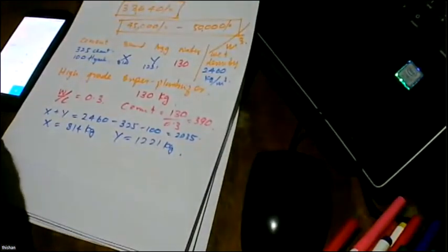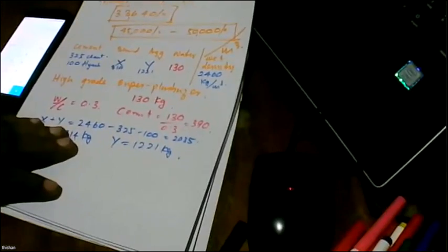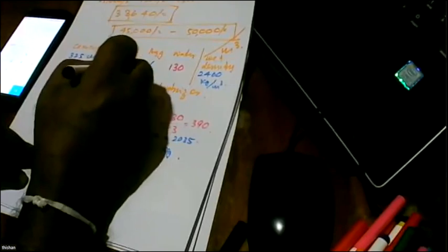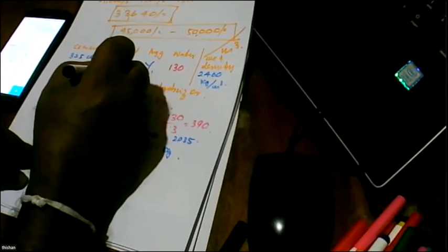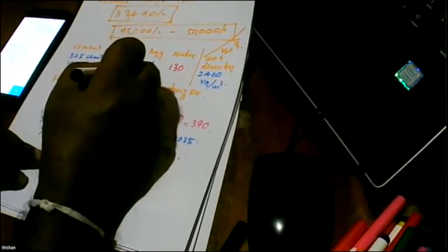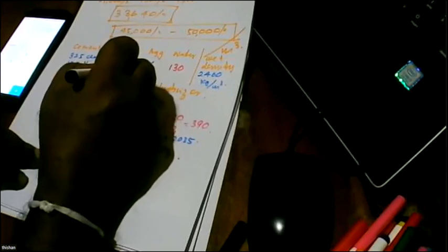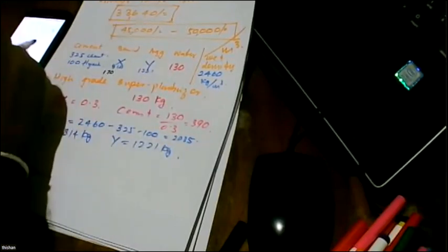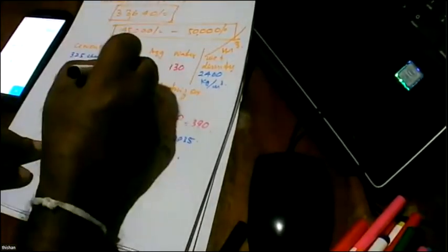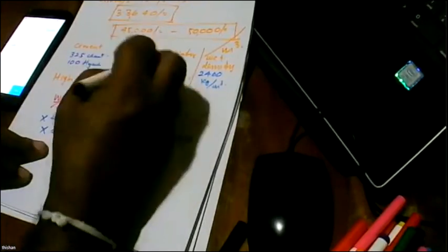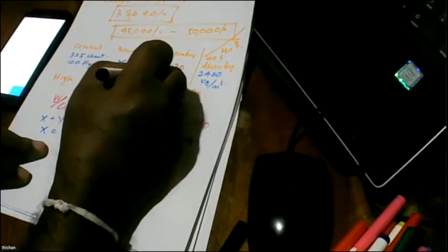Again, we can do something that is, generally we can add about 20% quarry dust. So 20% is about 160, we say 170, and 170, 840, 170, we get 644, and we can get chips 10 millimeter, 20 millimeter.